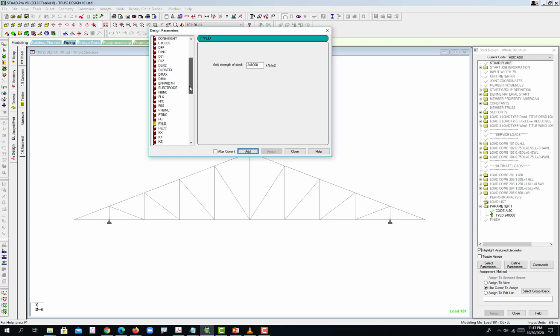And then our design, no? Our design checking would be your ratio, no? So this is the ratio. The ratio should be equivalent to 1. If that is greater than 1, then we're overstressed. Okay. Allowable divided by the actual stress should be less than or equivalent to 1. Now, permissible ratio of actual to allowable stress, you set that 1 to 1. So that would be our checking if any member of this model would be failing. Okay, so hit add. So that would be ratio there.